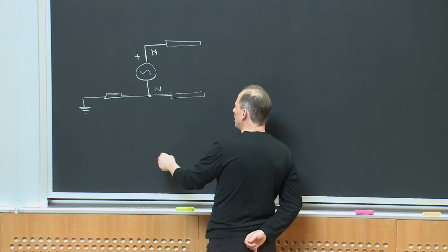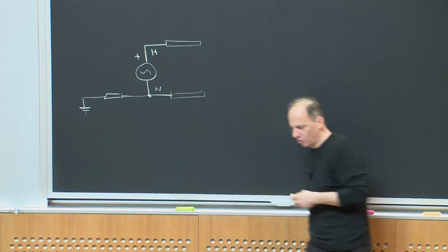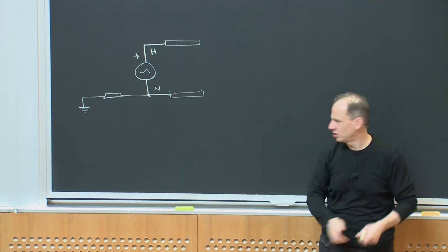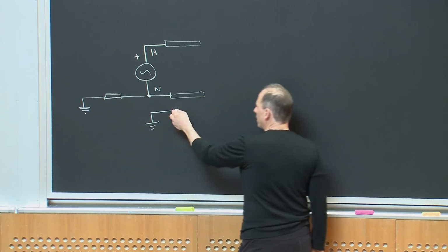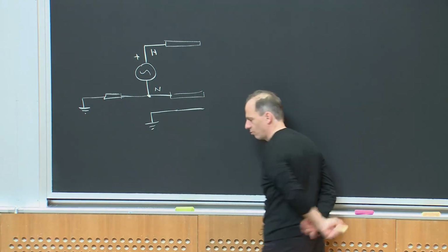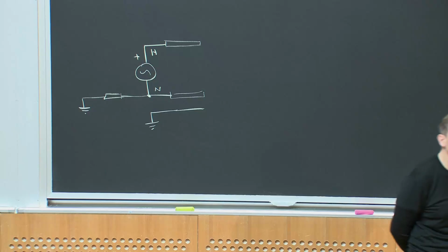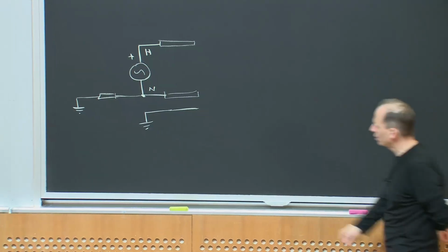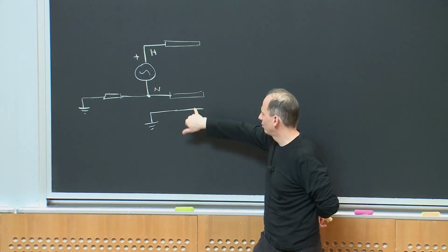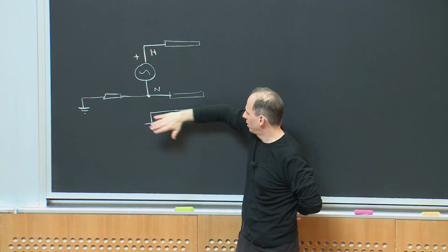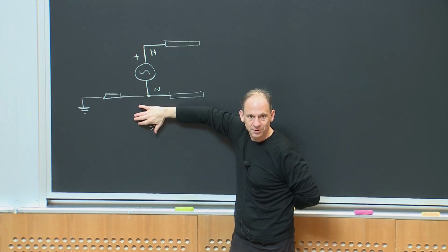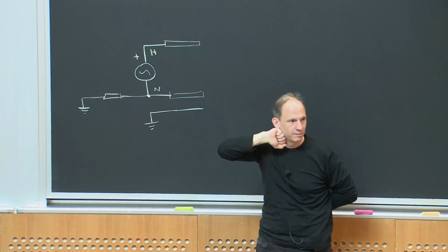And you know, it'll be close somewhere, right? And very often, if I think about what wires are going out to the boxes, usually there will also be a ground wire that's connected to ground, right? And that's usually the green or the uninsulated wire. And if you have a 3-terminal plug, one of those goes to the ground, one goes to neutral, one goes to hot. Okay? If you have a 2-terminal plug, they get rid of this and they just don't have an explicit ground going. Okay? Make sense, everybody?